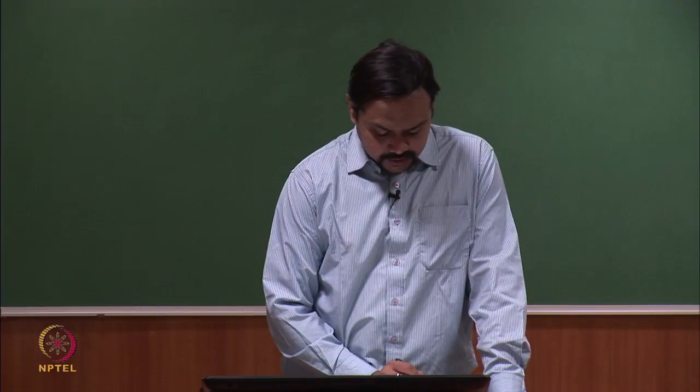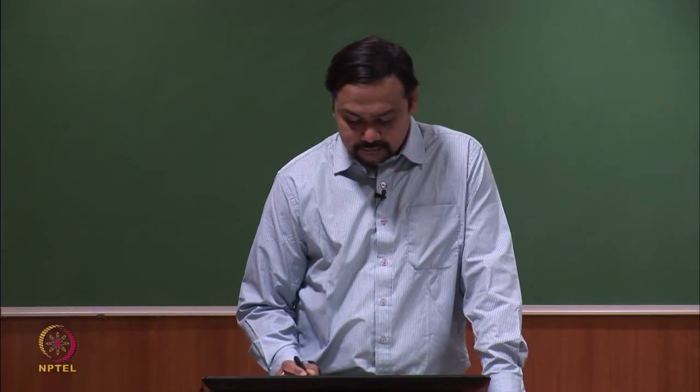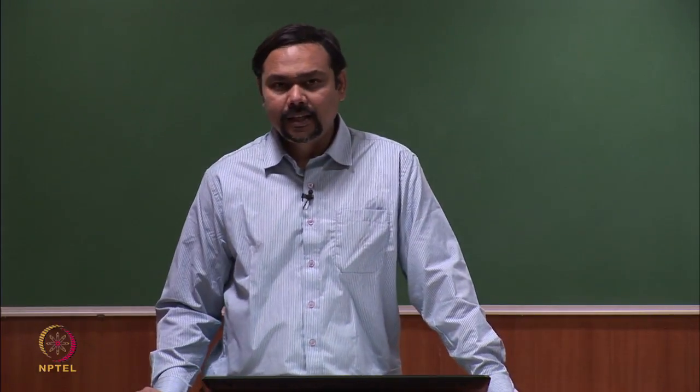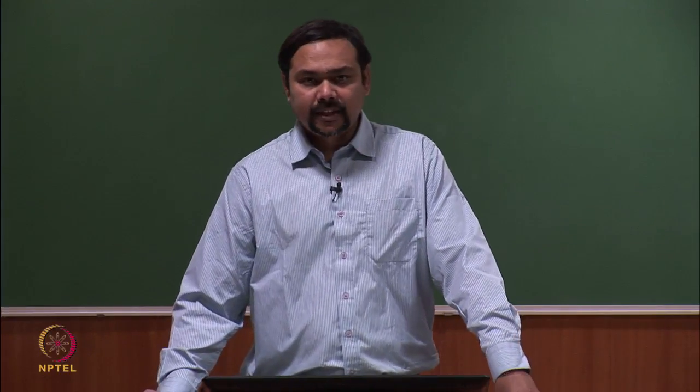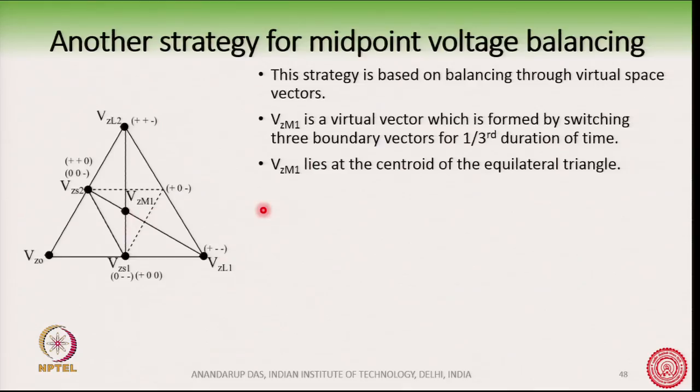Now we see one interesting technique for balancing the midpoint voltage with the help of virtual space vector. Now, what is a virtual space vector? A virtual space vector is a space vector which is formed by using the normal space vectors, okay, but for